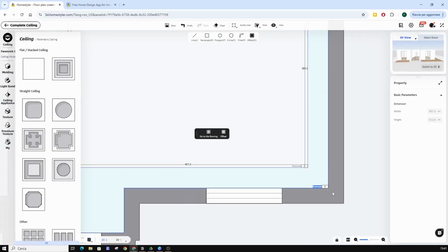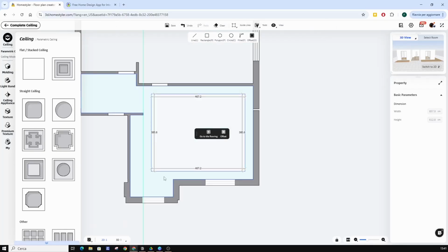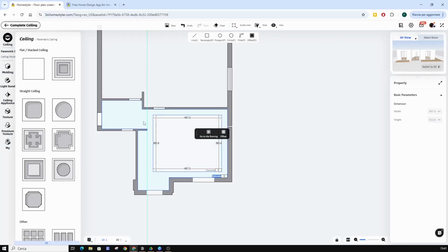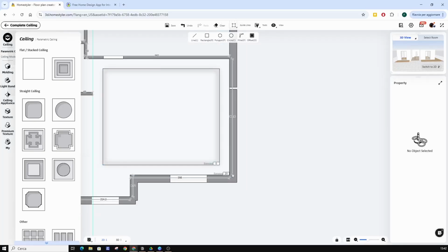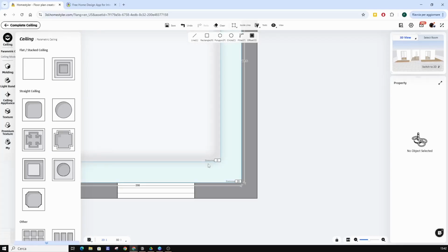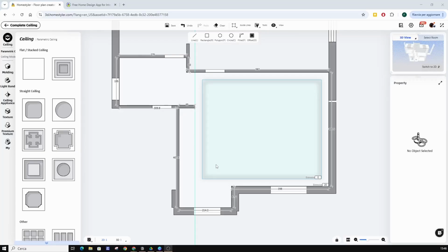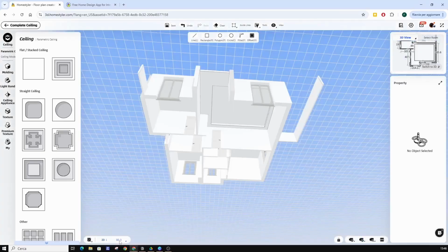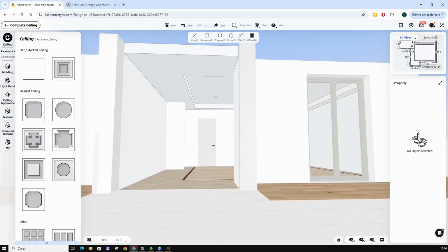We can decide, through the extrusion box, how much to drop the individual areas. For example, we want to drop the external area to create a dropped ceiling in this position, and so we can enter the value 20. Also, in this area, the extrusion box is present, but we leave it at 0. Let's go check in 3D what we have created. We see that we have a ceiling with a central frame and a perimeter drop ceiling.